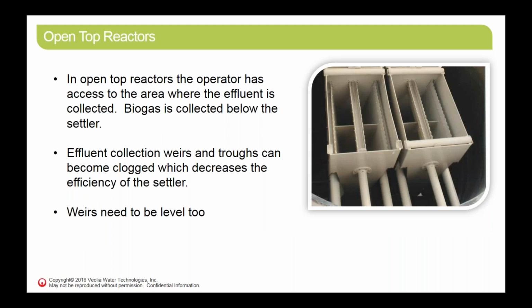So for the open-top reactor people out there, a lot of people have UASBs, and a couple of the high-rate biobed systems do have open tops. You should be doing some routine maintenance on those settlers. You can take off the cover panels, but be careful when you take them off. Safety issues: have your H2S detectors. Don't stick your face right down in it. You get overwhelmed with a puff of gas a lot of the time because they are gasketed down there.